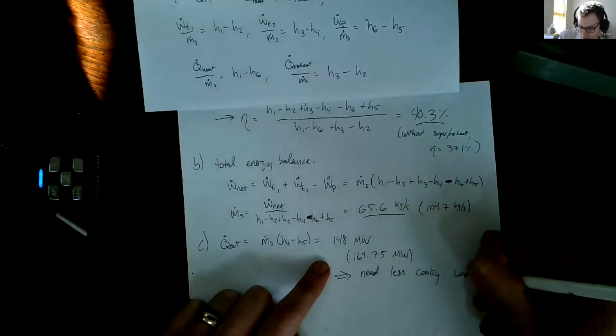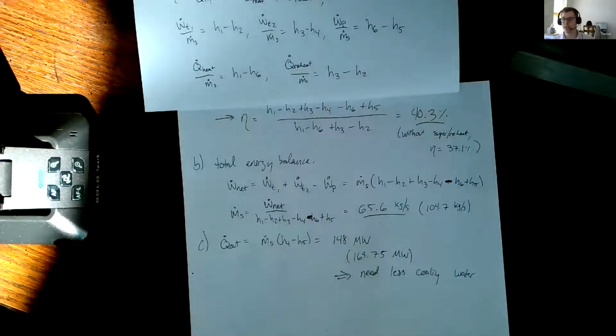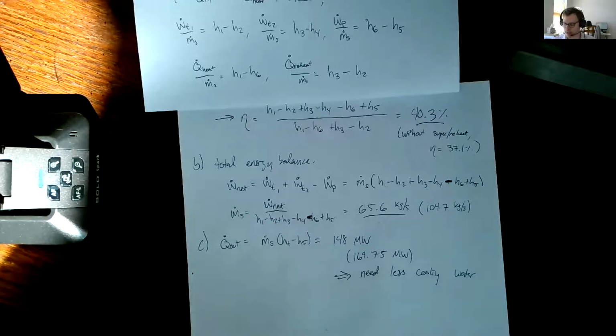cooling water, which is also a benefit, right? Smaller pipes, and if you're pumping your cooling water actively, that means your pump doesn't have to work as hard, so it's less expensive to operate. So all good things are happening because we've added superheat and reheat.